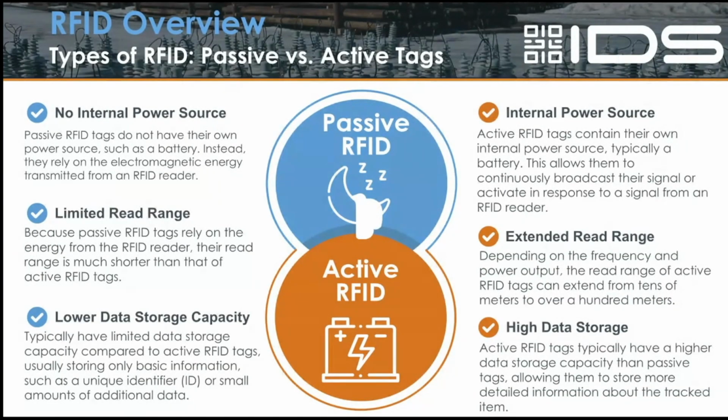So in our world, when we talk about RFID and specifically really our evolution as a product, it really comes down to two different types of RFID technology: a passive RFID technology and active RFID technology. The main real difference on a passive is that we do not have power in the tags. So we have an RFID tag that's got a little chip in it. Basically, it allows the reader to excite that chip, and then we can read that tag and then do something with it.